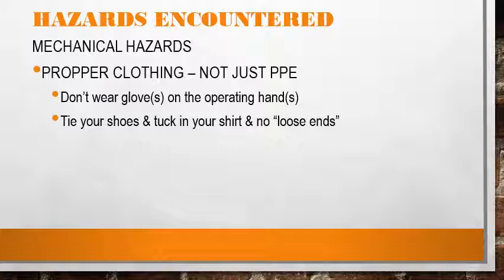Tuck in your shirt and don't have any loose ends, like the strings that come out of the end of a hoodie. Don't have those hanging off. If one of those gets stuck in a power tool, it can very quickly tighten and pull you toward the powered end of the tool.